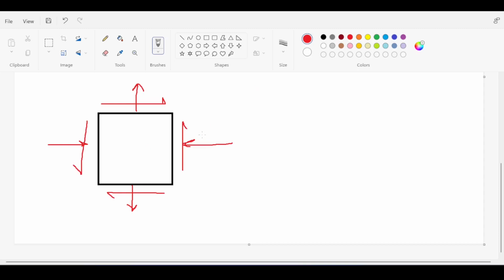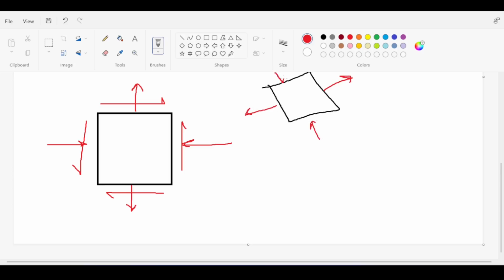Of course, this is a general case of stress, and of course, you can flip this or rotate the element in such a way to create maximum compressive and tensile stresses, which are called principal stresses. And if you have principal stresses, then your shear is zero, maximum tensile, for example, and compression. And you can have another element where you have maximum shear. In this case, the tensile and compressive stress are the same, and they are the average stress. I'm not going to turn this into a mechanics of materials lecture. I teach this anyway, but I just want to remind you of what you studied in the university.